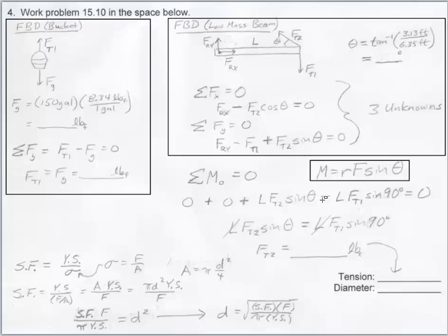Also have a minus sign here because if you put your right hand, your fingers here at the origin and extend them along the beam and curl your fingers back toward Ft1, your thumb is into the board, so therefore it's minus. If you then move this term right here over to the other right-hand side of the equation, you get something like this right here. So the minus sign goes away because you're adding this whole thing to both sides.